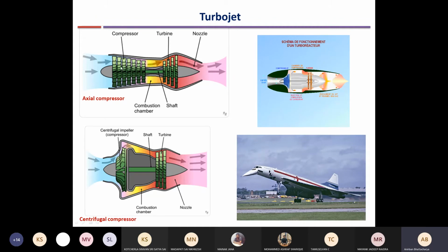So this increases the drag as compared to this. So this is a big drawback. And another point is that this flow direction is not aligned to the combustion chamber direction. So you have to again move the flow in another direction to bring it to the combustion chamber. So this is not as simple as an axial flow compressor. So nowadays all the jet engines that are used use axial flow compressors. Okay, but in the initial designs, we had seen that the British design used a centrifugal compressor during the Second World War, and the German design used an axial compressor.